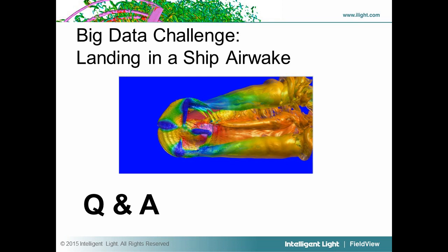It's got a number of capabilities. It has a full finite element solver, Sierra, inside it, so you can do full structure analysis coupled to the CFD. It's also got a linear modal structural solver. We don't do chemistry. It's got, like I said, the unstructured solver near the body, and Cartesian adaptive mesh off body. And yeah, those are kind of the big features. I know I'm missing some.